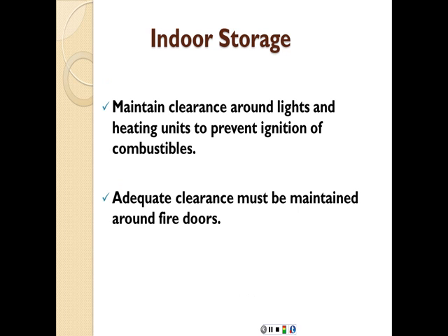Maintain clearance around lights and heating units to prevent ignition of combustibles. So do not store the combustible material too close to a source of heat or a source of fire where it can cause that ignition. Adequate clearance must be maintained around fire doors, again because the fire doors are going to be used to enclose the fire. In case someone is inside, they need to get out, so you need to have easy and free access in and out of that room.